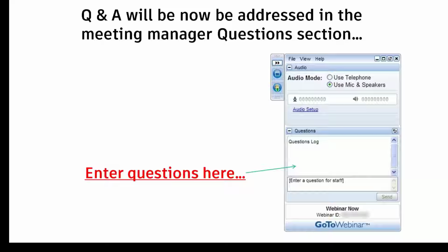One last question here before we call it. Kendra had mentioned working with imported models. If the models are coming in intact, they're solid, they don't have any warnings or errors on the import, they'll work just fine in the FEA environment. What sometimes happens is, if you were to import an STL file, for example, the STL file is most likely not going to be solid to start from. And so you would have to do work on it in order to make it functionally solid before you could really use it in the tool.